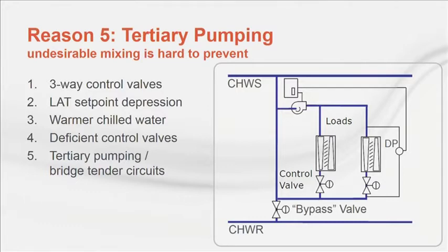Sometimes they are installed under the guise of increasing system delta T. Unfortunately, they often result in exactly the opposite and dramatically decrease system delta T. The problem lies in the presence of the bypass valve in the circuit.